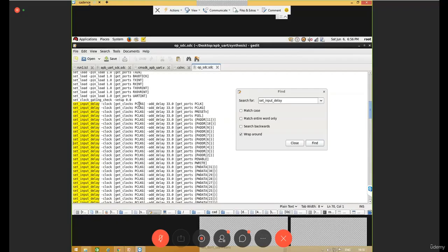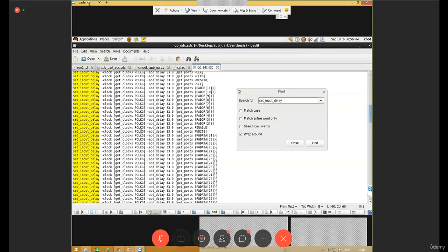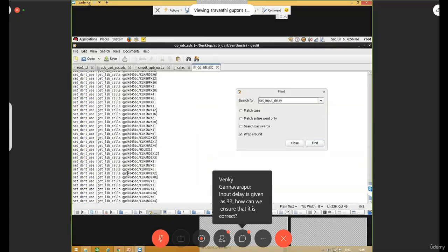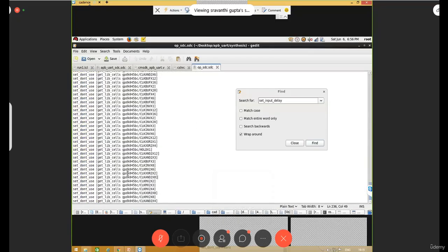Basically, we are not using those library cells while converting to the gate level netlist. This list of set don't use cells comes from the tool itself. Manually, you should not give it, because during optimization the tool does not pick or touch those gates. The tool has marked those gates as set don't use.